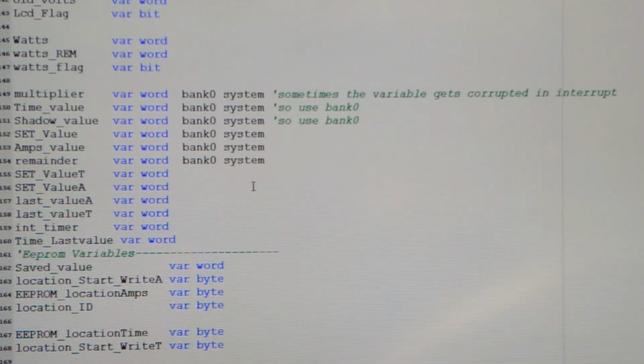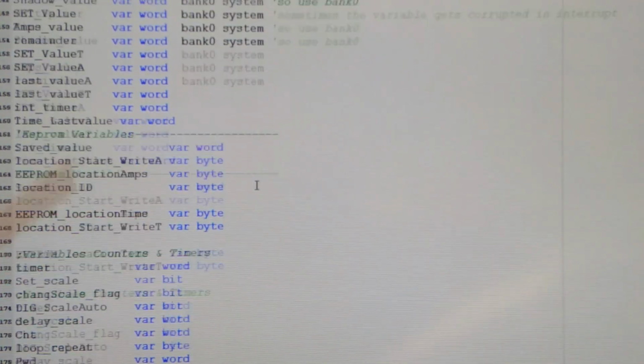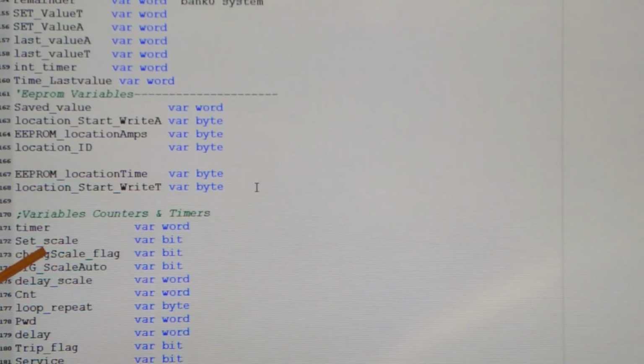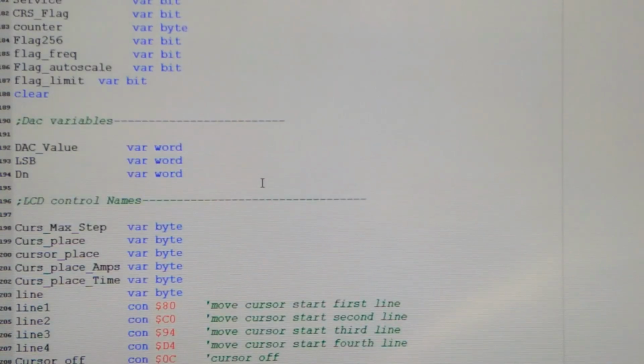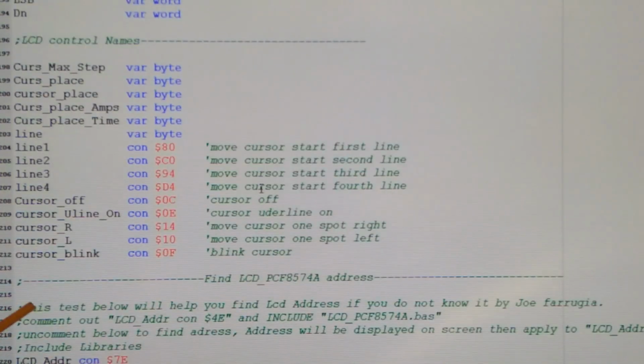The assembly interrupt system is what most C compilers use. But PicBasic Pro, again, it might sound like they're making it easier for you to have a compiler, it does it in the compiler, which means it adds extra code when it compiles it for an interrupt.